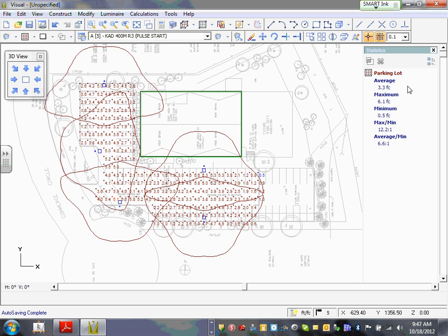Flip them by typing right here. It says orientation when you're dropping them. Right here. Let me drop one here. Here's my orientation. Can you see where it says orientation here? Just type 180 to flip it this way, or 90, or 270, and so forth.